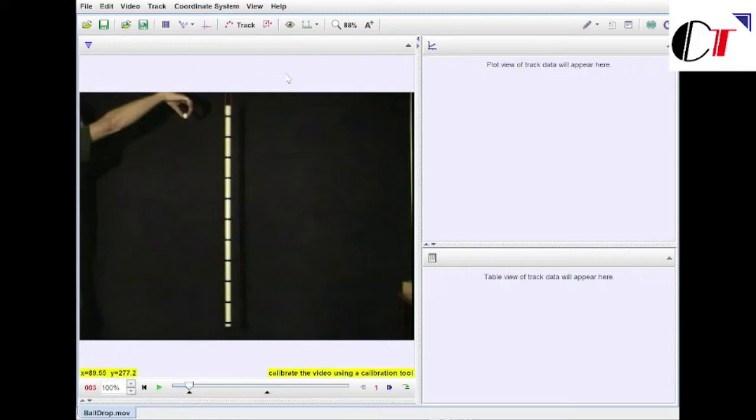So if you look at this again, it's just in perfect order. You start with the clip settings, and then the next button is the calibration. So you just go to new calibration, and then the calibration stick appears. And in that video, the dimension from the top mark here to the bottom mark here is just 1 meter. So this is exactly the calibration that we will do.